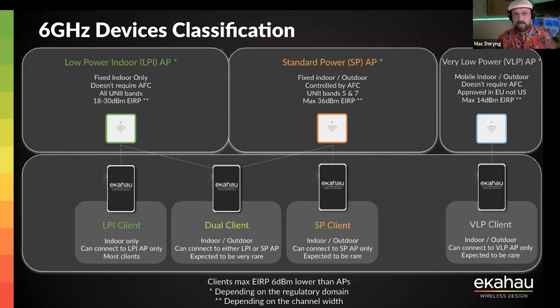So what it means is that we are allowed to use Wi-Fi 6E inside, without further restrictions, using LPI class devices, but access points have to be physically mounted. They cannot be mobile. They cannot be battery operated. You can still use UPS, of course, but they can't be mobile AP devices. They cannot have external antenna slots, so you cannot just attach a high gain antenna and not abide by the rules set by the regulatory bodies anymore.